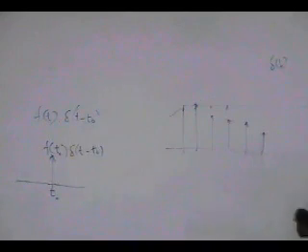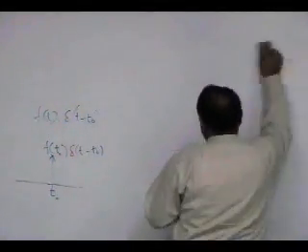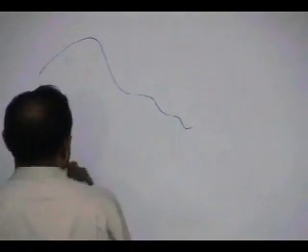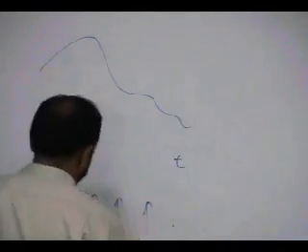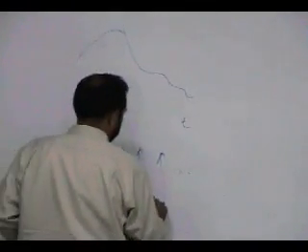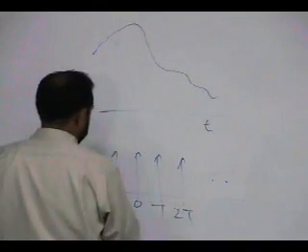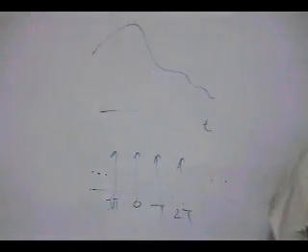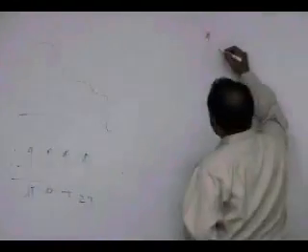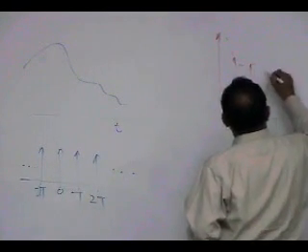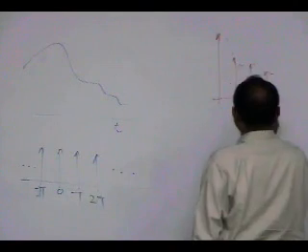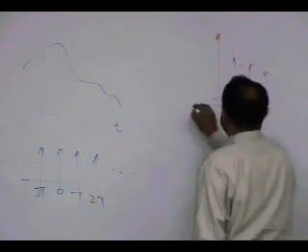This is what in time domain. All we are saying here is that if you multiply a signal, this is your signal, with a train of impulses at every 0, T, 2T, minus T. So as a result, this is what you get. Still at 0, T, 2T, minus T, and so on.